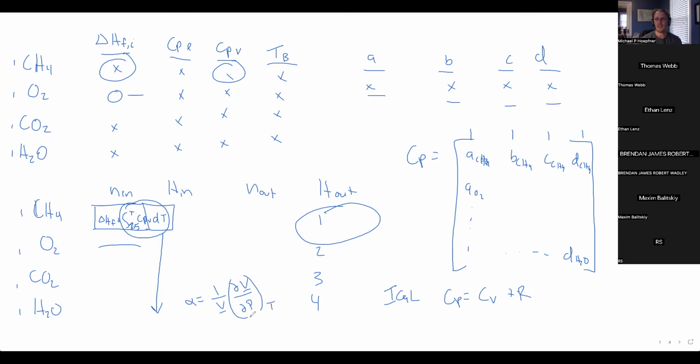I think it's alpha, and I think that's the definition for the isothermal compressibility. But you'll find that you have to pressurize liquids a lot before their density changes substantially. If I wanted to change the density of a liquid by 10%, that might take a couple thousand atmospheres of pressure. Oh, okay. Awesome. Thank you. These are all properties that are measured. That's the fun in thermodynamics, trying to make as few experimental measurements as possible while getting the most data out.